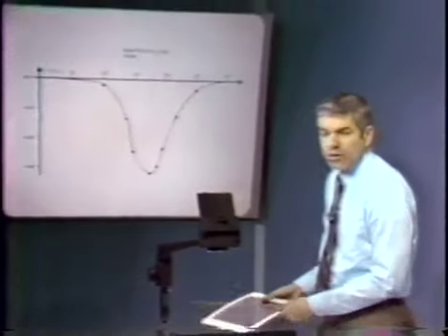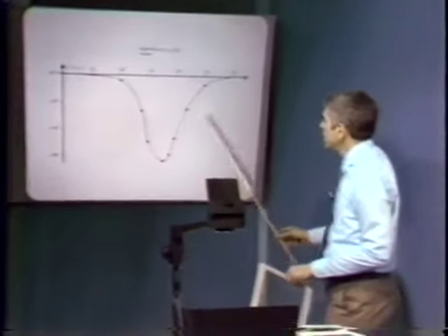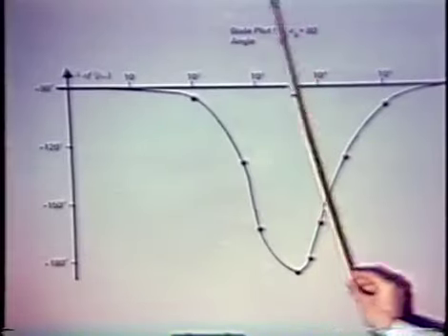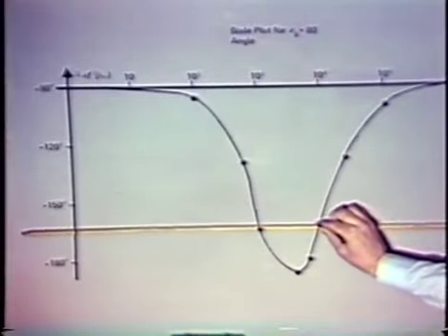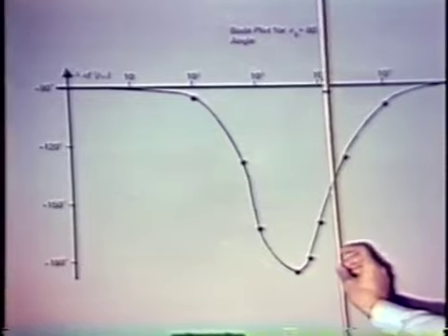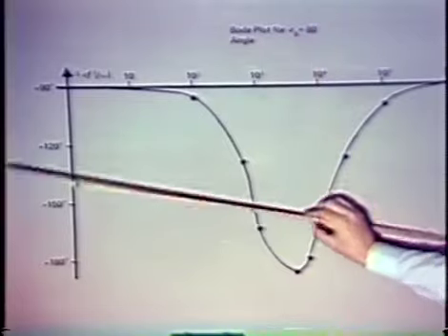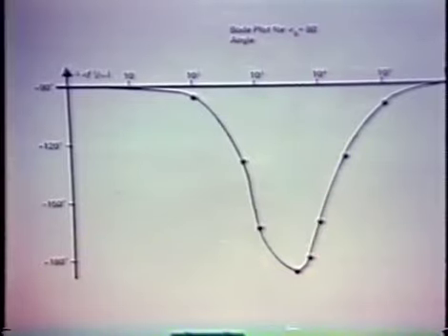Here's the angle portion of the Bode plot. If we look at 10 to the 4th radians per second, we find out that we have a positive value of phase margin. So again, with A naught equals 80, we'd be crossing over, as I had indicated in the original Bode plot on the board. We have a positive phase margin.